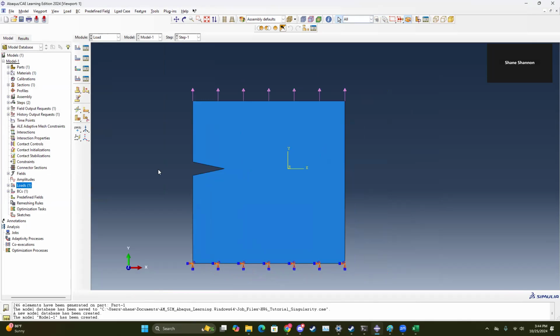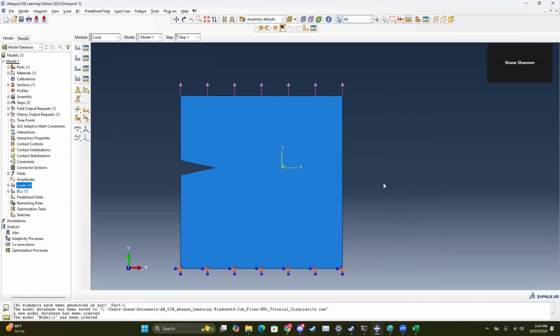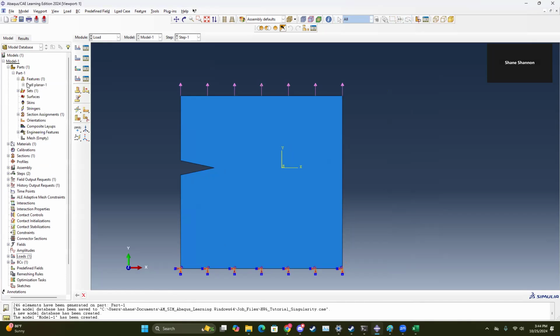When it comes to meshing, in his 1017 lecture, he goes over a lot about meshing and some things we can do to improve it. One of the things he mentioned, because for the student edition we're only limited to 1,000 nodes, is that you can instead cut this in half. What that entails is really easy when editing the sketch.